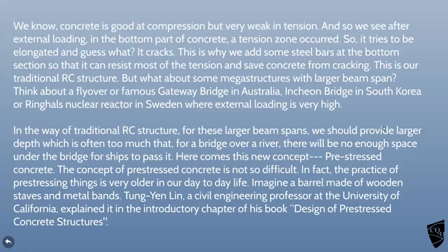Traditional reinforced concrete structures, those larger beams and spans, would be enormous in size, physically enormous. They'd be really massive, big, deep beams, which also brings the problem that they've got to support their own enormous weight, which makes them even bigger. So we get a new concept. We then come up and we pre-stress the concrete. We squash the beams from the ends, pull them together a bit so it counteracts it. So the loading has to overcome that pre-stressing before the beam starts to move.